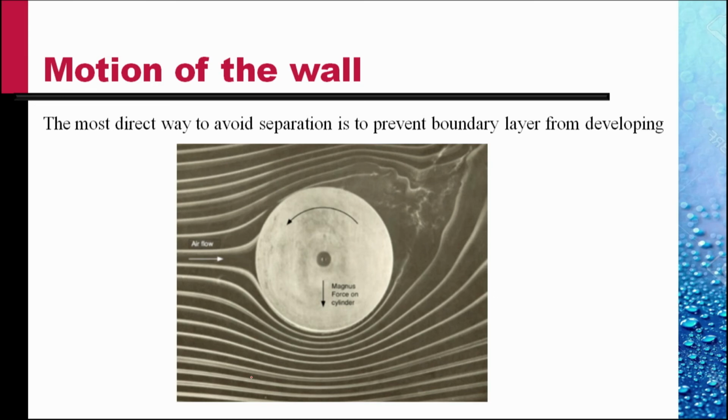So the boundary layer separation is delayed, quite reversed from what happens in the top, where the surface is moving into the flow, increasing the relative velocity, leading to an early separation.